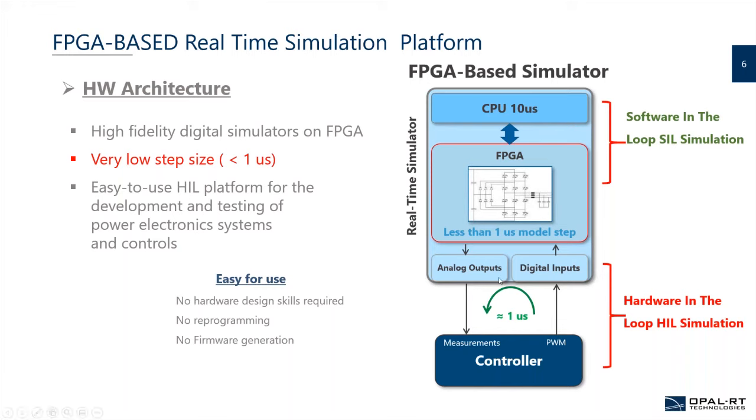Using the analog and digital input-outputs integrated in the simulator, the circuit can be easily connected to a real controller under test with a latency of around 1 microsecond, forming a real hardware-in-the-loop application for control or any device under test.